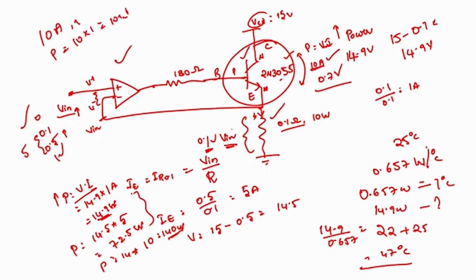So, that is the reason we are using a 0.1 ohm 10 watt resistor. If it is possible, try to go with even 20 watt, so that with the withstanding capability, you cannot even see any kind of heat on the resistor at all. Depending upon the operating current and the voltage drop, you have to choose your resistor. If you go with a higher resistance value, and if you use a transistor other than 2N3055 which can withstand even higher current, the same plant can be used for higher current applications, very fast temperature output applications too.